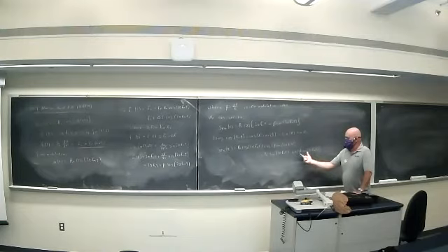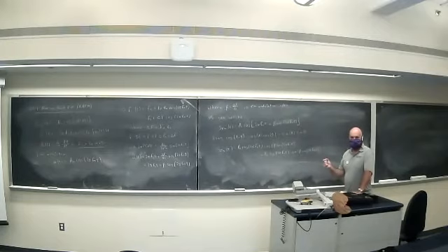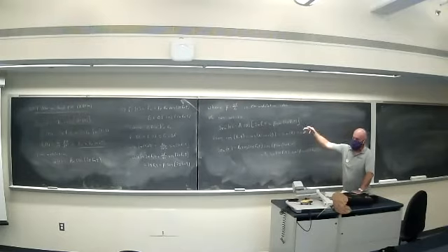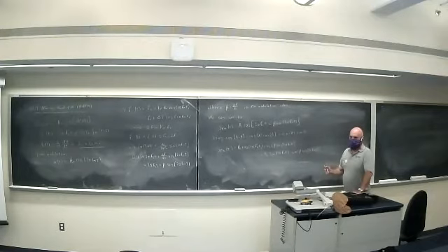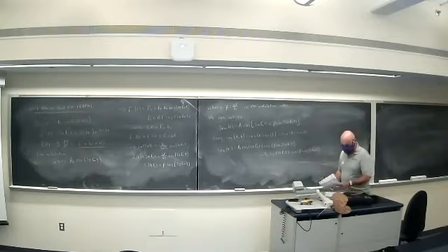Now, do you remember another common approximation that you run into in calculus and engineering, especially communication, sine of theta for theta small? Do you know what sine of theta for theta small is approximately? It's approximately theta, in radians. So again, if we restrict ourselves to the small beta case, and this is what corresponds to what we call narrowband FM, we can do another simplification. It's not true for large beta. We'll tackle that next time, but let's talk about this small beta case.